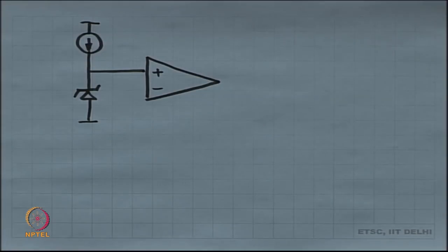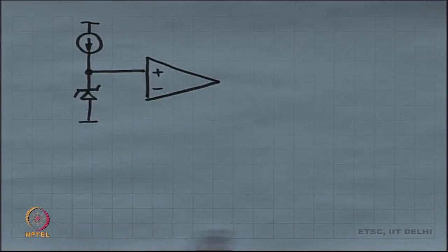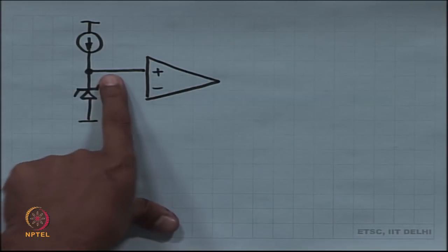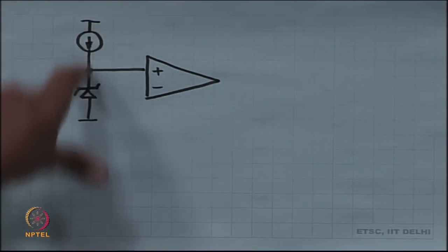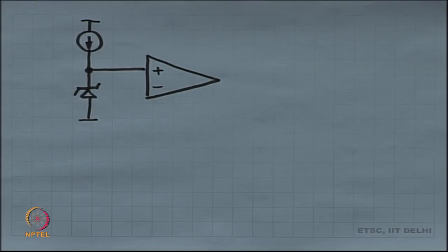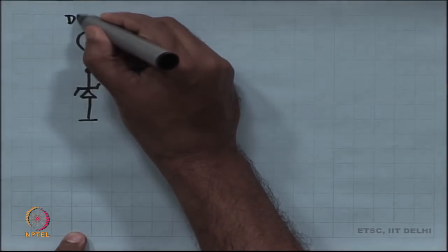This is the idea. A lot of people use this Zener diode. So, I take this Zener diode and create a constant voltage. I bleed a current through a reverse biased Zener diode and create a constant voltage. And now, this is from the dirty supply.